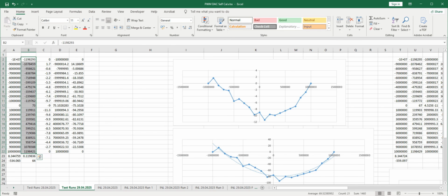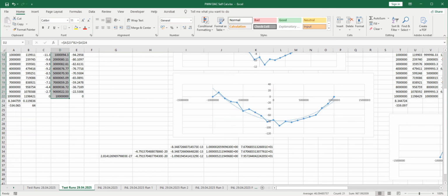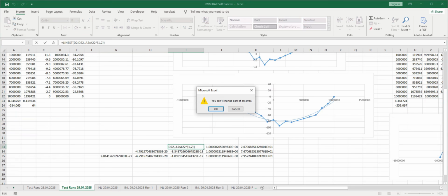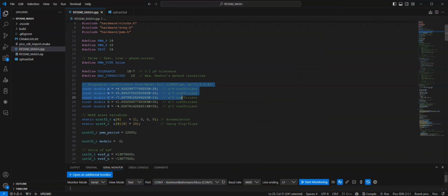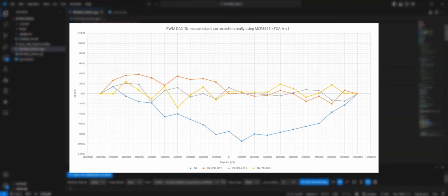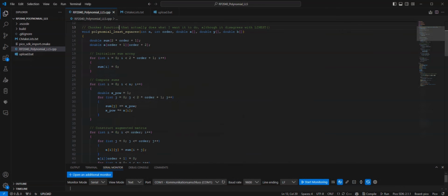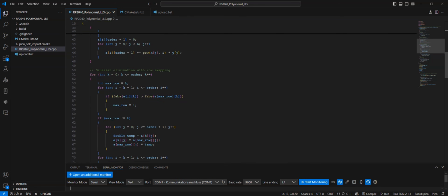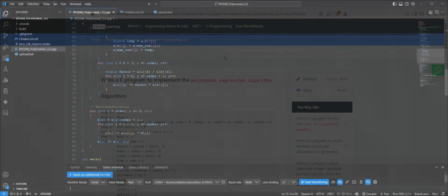With the ADC's INL error taken care of, I used it to measure the output of the DAC. Since the ADC resolution is different from the DAC's, I derive a slope and offset value that I can apply to the ADC's value so they correspond to the DAC's. These values are then used to calculate polynomial coefficients, which are loaded onto the RP2040 for correction. Unsurprisingly, the ADC is able to correctly measure the DAC's INL, and the calculated coefficients do indeed result in its cancellation.